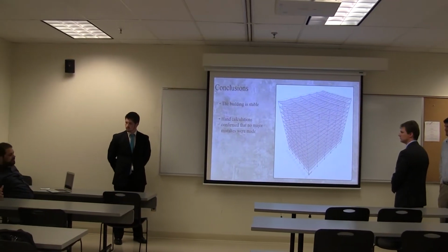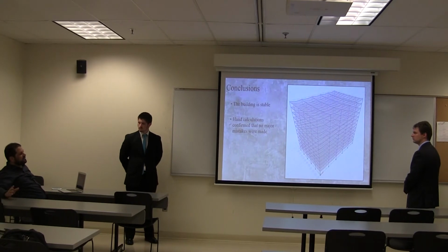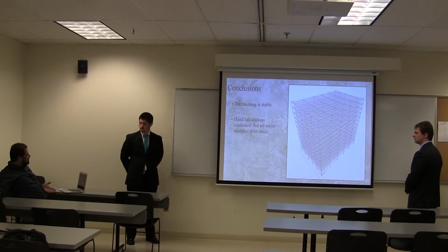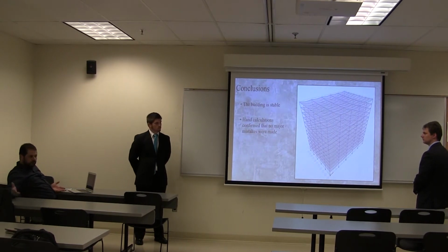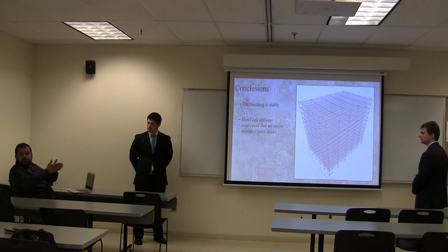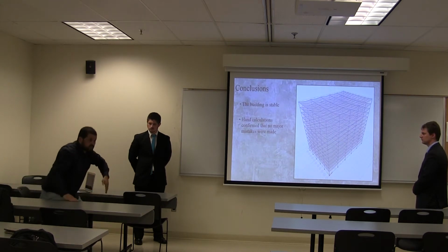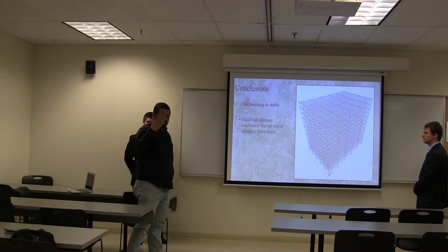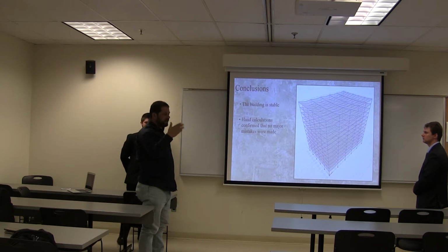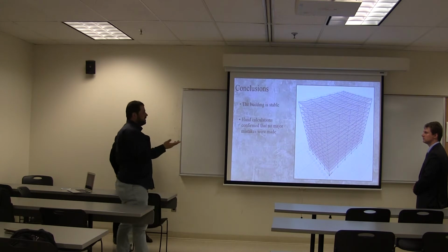When you verify something, you verify based on the live load, because I can tell you what the live load is. We have 100 psf, and the floor beam will have a tributary width of 10 foot. So for the live load by itself, it will be 100 times 10, which is 1,000 pounds per foot, or 1 kip per foot. What's the length of the floor beam?